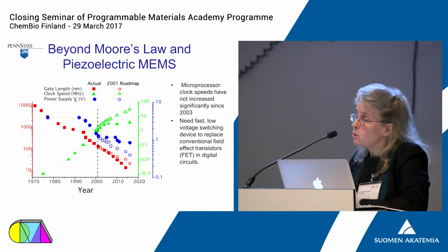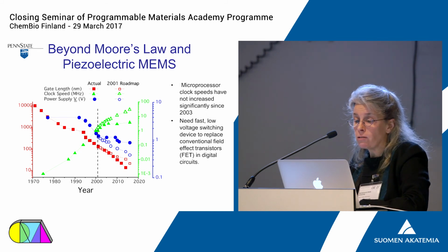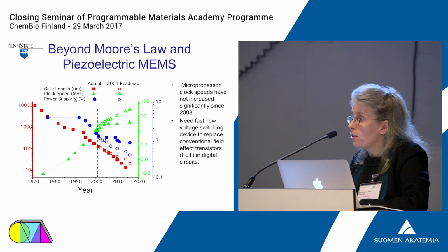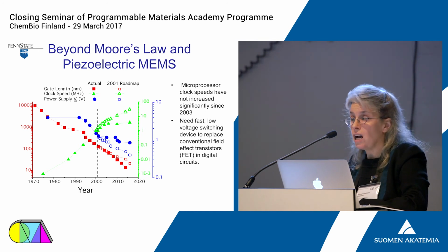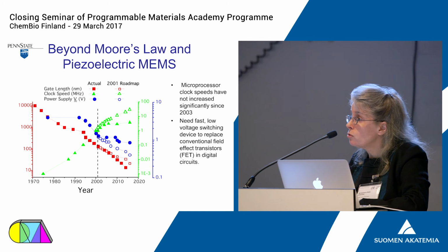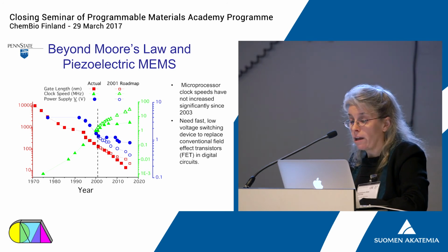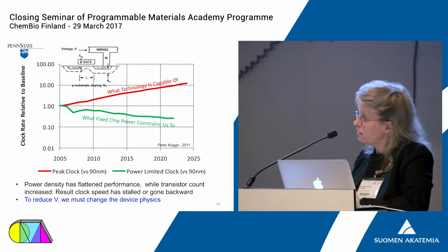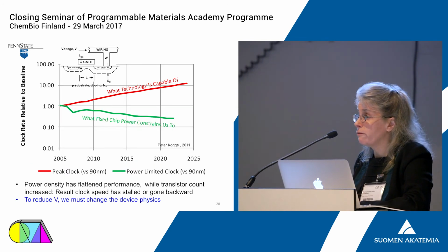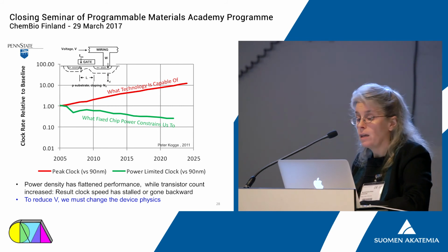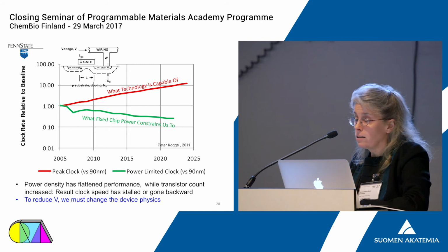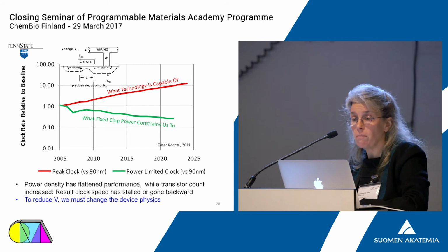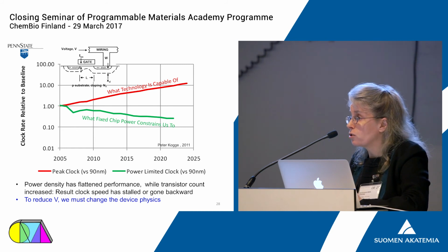And so the fact that we choose to carry around devices that are powered by batteries is actually driving us in the opposite direction, where we're choosing to run computers slower in order to have long lifetimes. That's a fundamental problem associated with the physics of the silicon switch. It turns on at 60 meV per decade. If you want to get around that, you need to actually change the mechanism by which the transduction occurs. So you have to change the switch.